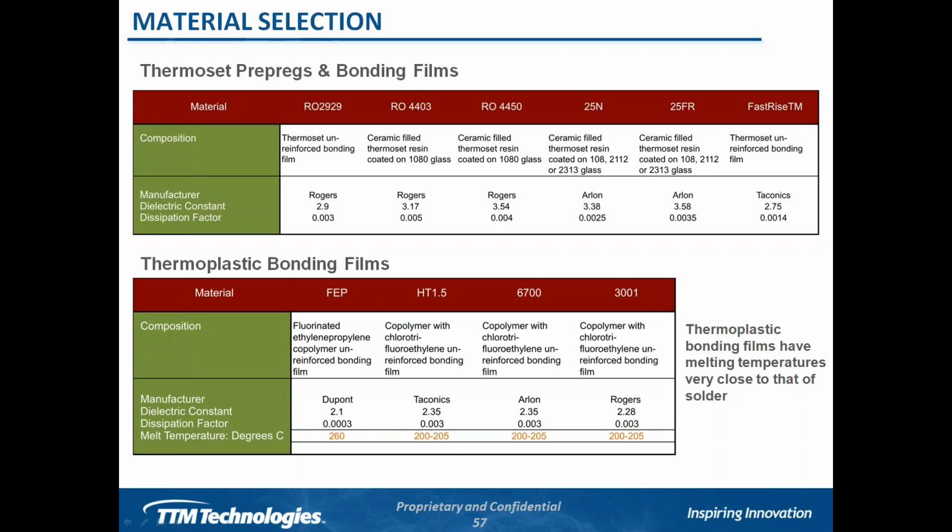So when you look at these great materials and they're like, oh, I like this Rogers 3003 material set, it's great. Understand that if you're making a multi-layer, at some point you need some sort of a bond film, and that bond film is not going to necessarily match that high-end laminate in terms of performance.